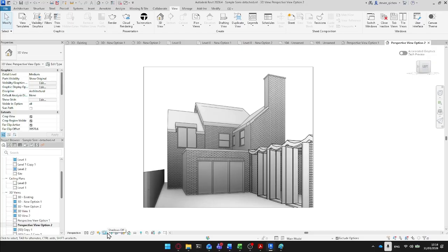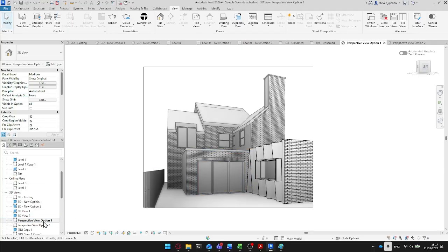Yeah, for each of your views, make a duplicate of that view, and in the visibility setting, set it to show that option. Only, yeah, when you're editing it, you need to change it to the correct option, as long as you have the option selected. Realistically, it's quite annoying to switch between this and this all the time.